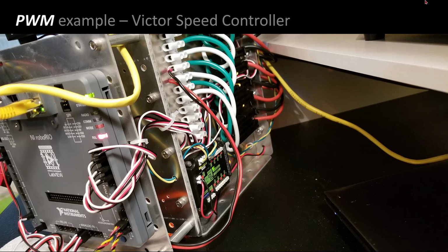We will be adding the Victor SP speed controller as control of the PWM signal. In our last session we connected two servos, which you can see right here at the bottom. Here we're going to be taking one of these PWM signals that's already wired into a Victor SP, which is a fairly generic PWM speed controller.